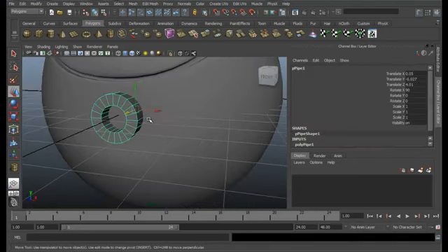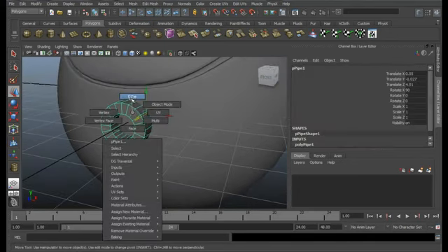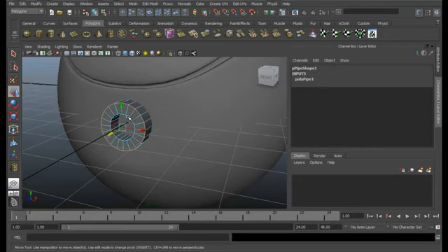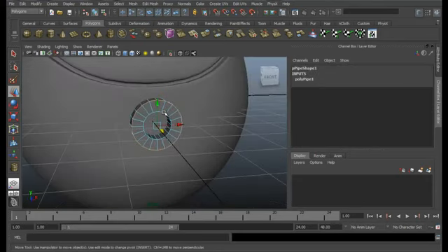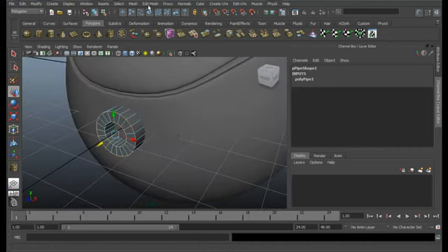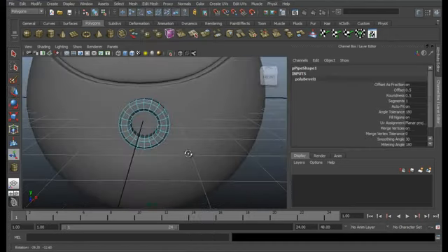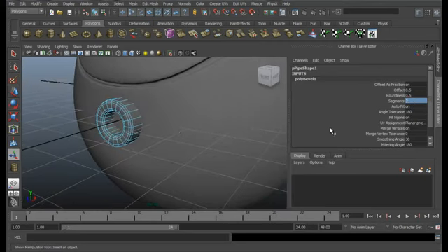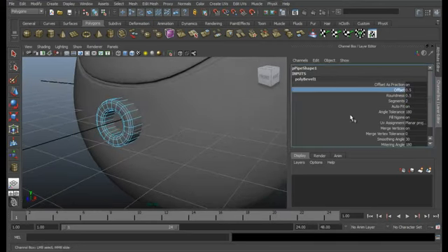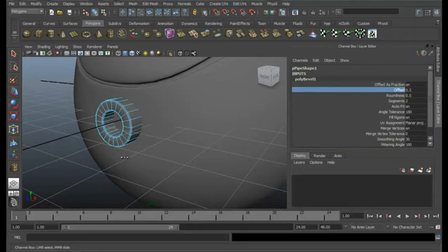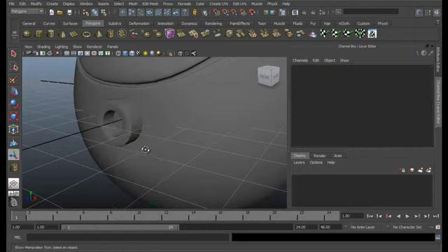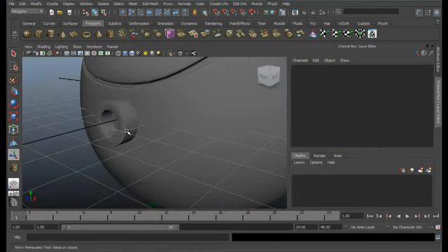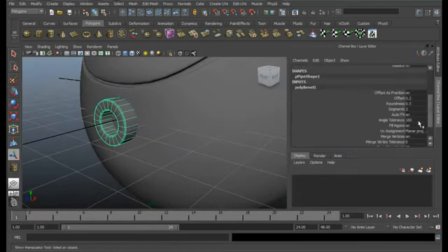Now select the poly pipe and then right click, go to edges, select the corners. Okay, and go to edit mesh, bevel. I always like the hard corner edges beveled, so 2 segments, and then play around with some offsets. Just try to get some good result. So it's alright, or let's use only 1 segment. That'll be good, I think.